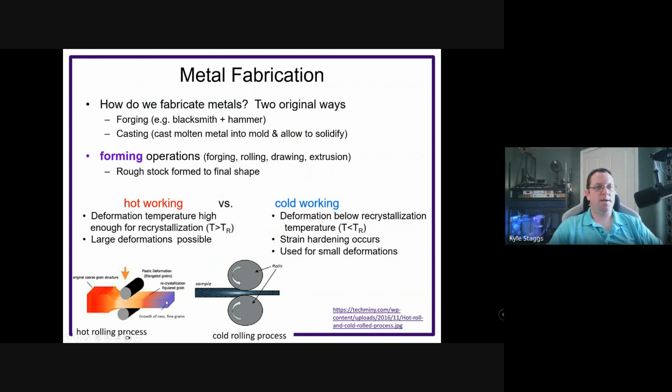The finer the grains, the more resistant they are to movement. The bigger the grains, the less resistant they are. So the more ductile the material going in, the harder the material that comes out. Especially in the case of cold rolling, you can think of it as literally just smashing these grains together, and you compress them in a way that makes it very strong in this direction.